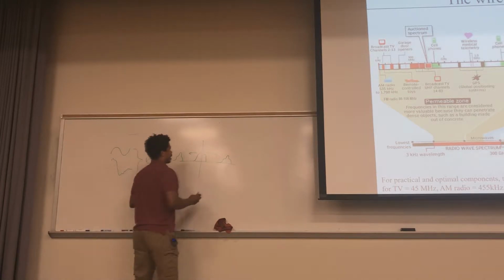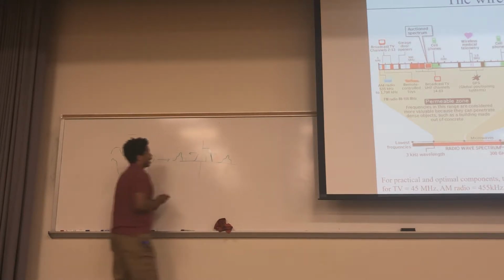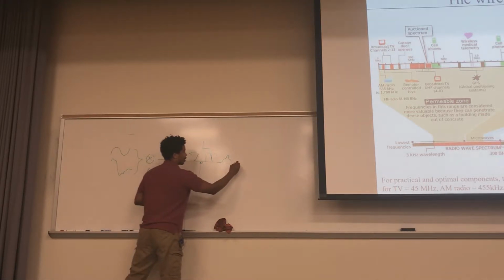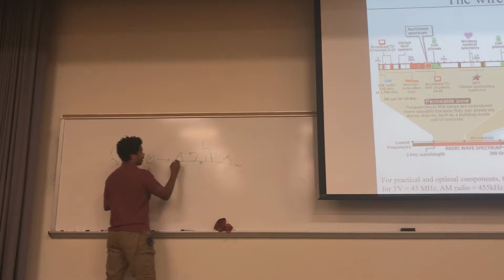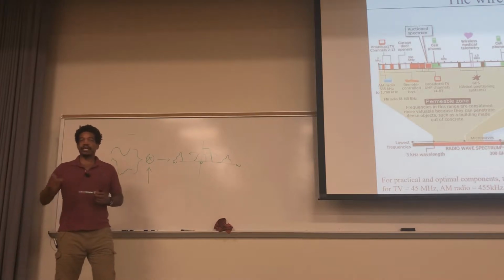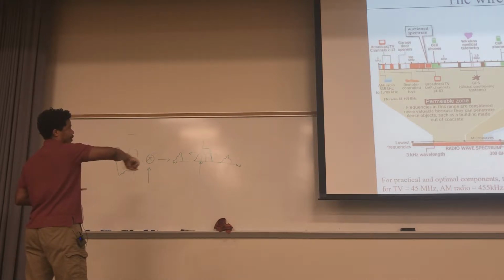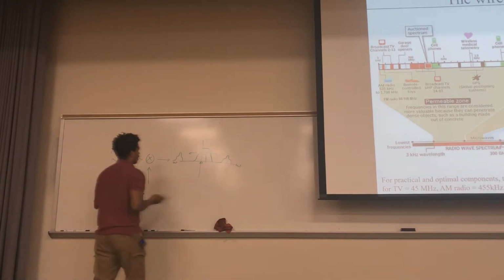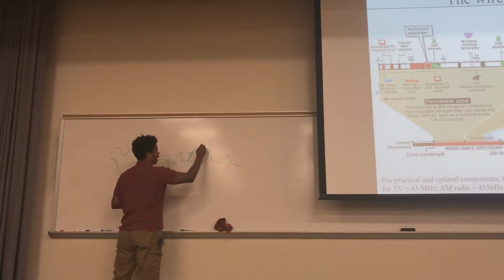So what you typically do is send this through a low pass filter like that. This is 0 frequency, and here's some other frequency out there. What happens is you will filter out these frequencies here and here. This frequency over here is negative. So here are positive frequencies and negative frequencies. When you see negative frequencies, it just means that instead of going around counterclockwise, think of it as going around clockwise, and that's the negative frequency. Okay, so you can think of it like this for your low pass filter.